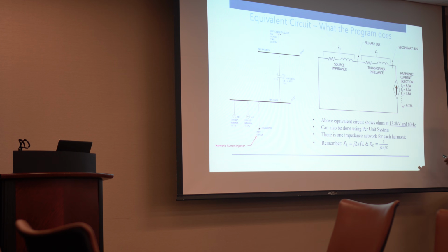I think in ETAP, when you put in the filter parameters, it wants single phase kVAR for the filter. For EasyPower, it wants 3-phase kVAR. It's not immediately clear when you pull up the window and type in the values what to enter. So in the end, you have to do some type of validation, because you can see the calculation here is easy.